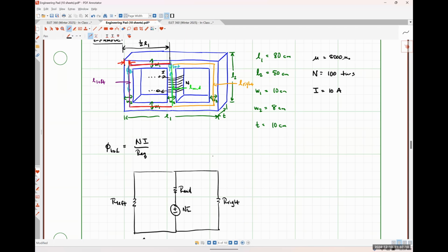So all of our basic circuit analysis techniques that we've learned in our previous classes can be applied to magnetic circuits, as long as we remember that everywhere that we had a voltage in an electrical circuit, that's what our MMF is. Everywhere we had a current in an electrical circuit, that's what we are now considering flux. And everywhere we had a resistance, we now have a reluctance.